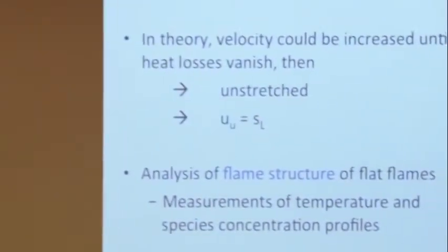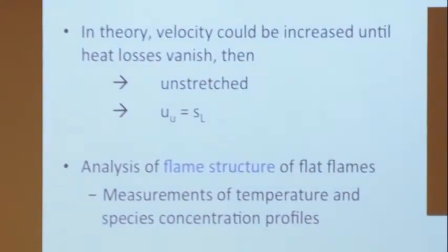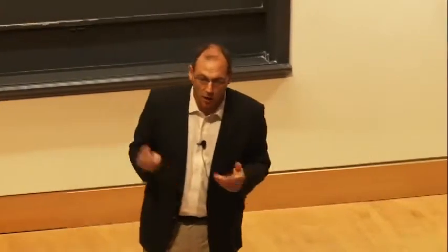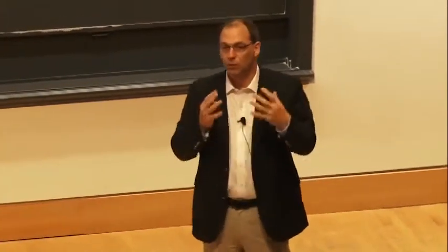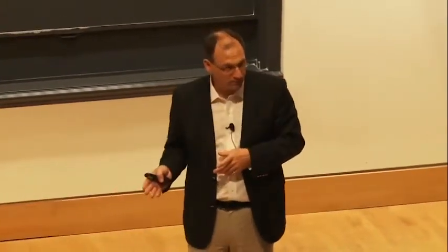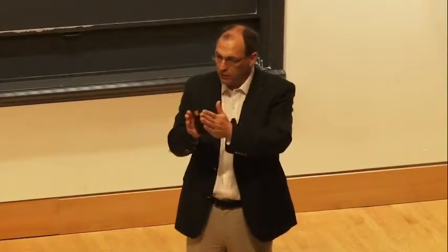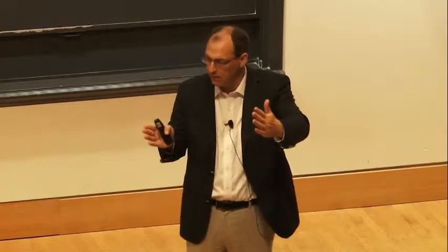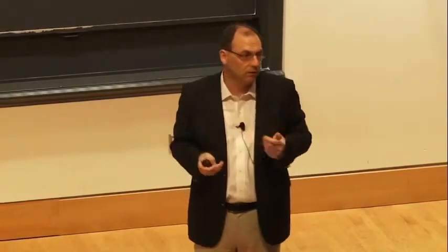One of the problems is this thing is still very thin. It's very thin, and it's hard to measure in a very thin layer. So what people do often with these also, is to run them at very, very low pressure. You go to very low pressure, the flame becomes very thick. And we'll see later on why that is. It becomes very thick. And if the flame is very thick, you can easily do measurements.